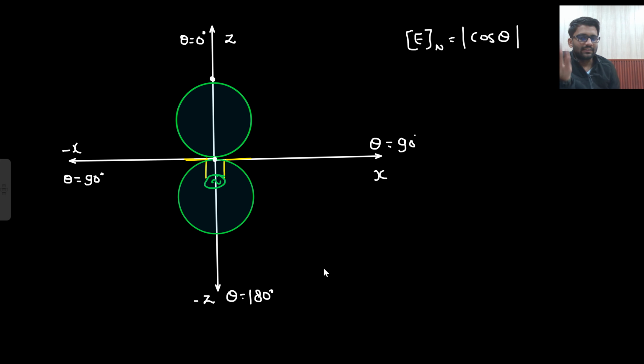Okay, so yeah, this is not the standing wave pattern, this is the radiation pattern. And we are not going to draw that H-plane pattern. It is pretty obvious how the H-plane pattern will look. That would be a circle only, so we don't need to plot it. So forget about the H-plane pattern. The E-plane pattern we have drawn. This is how the radiation pattern will look. And if the question comes in the examination, then this pattern only will be made.